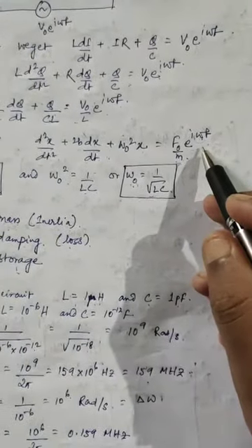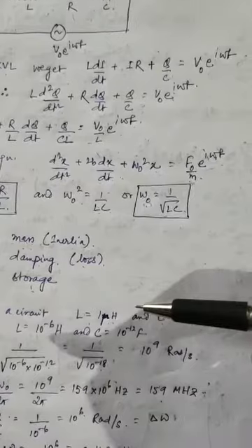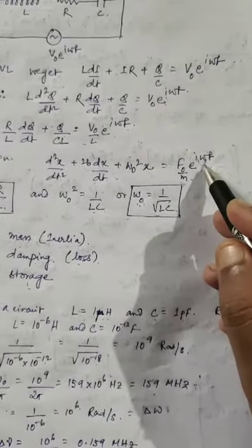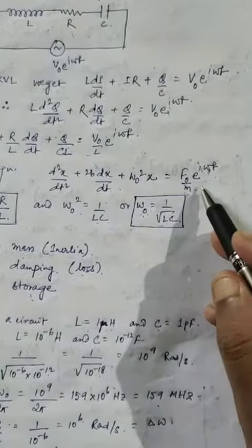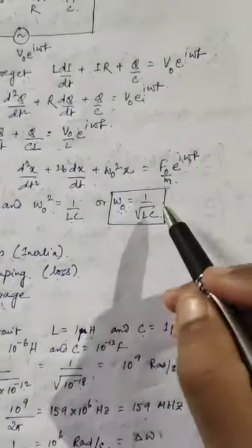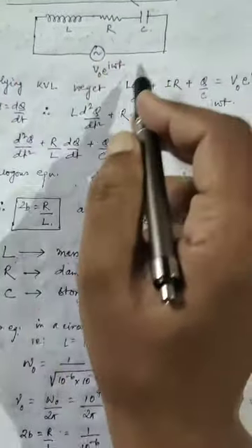So the radio wave is falling on the circuit, but let's say the frequency of that radio wave is not matching with the natural frequency of this circuit. You know from resonance that if it does not match, then the power will not be delivered much. So there will be very low current through the circuit, and the circuit will be approximately off.